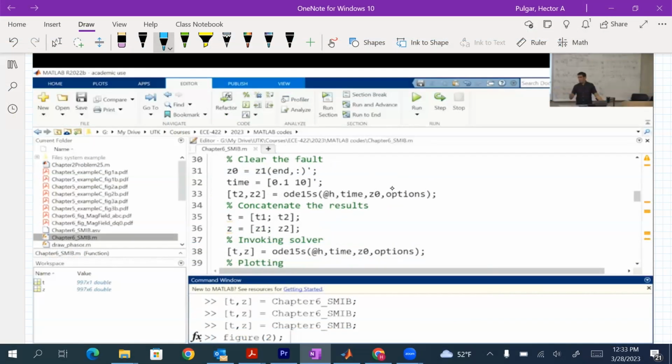Here I have a screenshot of the code. So at the beginning, we calculated the state and algebraic variables during the short circuit, and then we did it after the short circuit, and we concatenate the result. So T and C should have the result we needed. But then in line 88, I was overriding everything again. So this line remained from the previous work we were doing. So basically the mistake we had was we forgot to delete these lines.